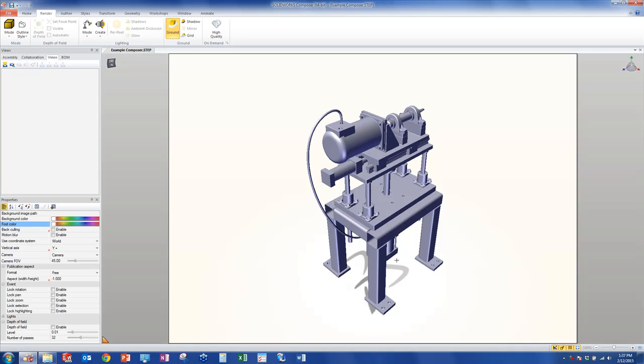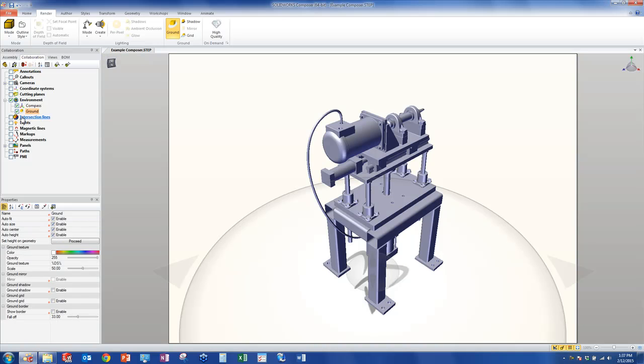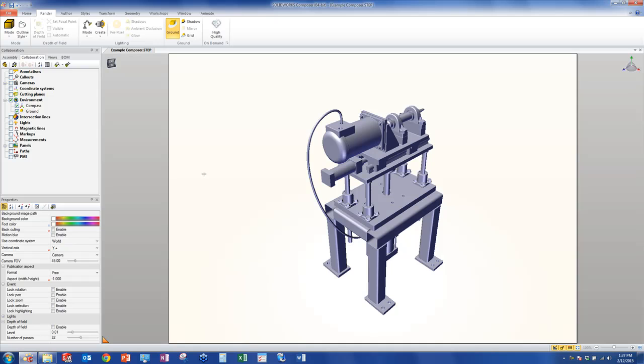Now you'll notice that currently there's a little emblem down here. In my default template I have the Dassault products emblem. I'm going to turn that off for this example. To do that, I'm going to come up to this collaboration tab and choose the option called ground. When I choose ground, this gives you the ability to remove or even add new emblems that would be sitting on the bottom of your preview. In this case, it's set under ground texture. I'm going to backspace through that ground texture so that there is no more image down there.